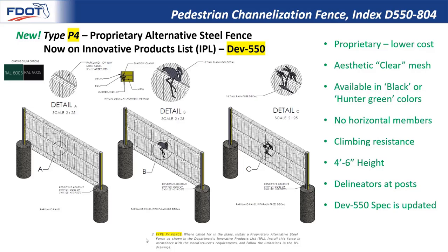The standard plans instructions has also been updated to give some guidance on this proprietary fence. And last, the pay item for Type P4 has been added to the BOE and it's now available. And so when considering the use of pedestrian channelization, please consider the Type P4 proprietary fence. It's actually a pretty state-of-the-art design that's used elsewhere by the industry for security of government buildings and important landmarks, and so it's very durable and difficult to cut. And as mentioned, it's difficult to climb while also being of lower cost than our legacy fence design.